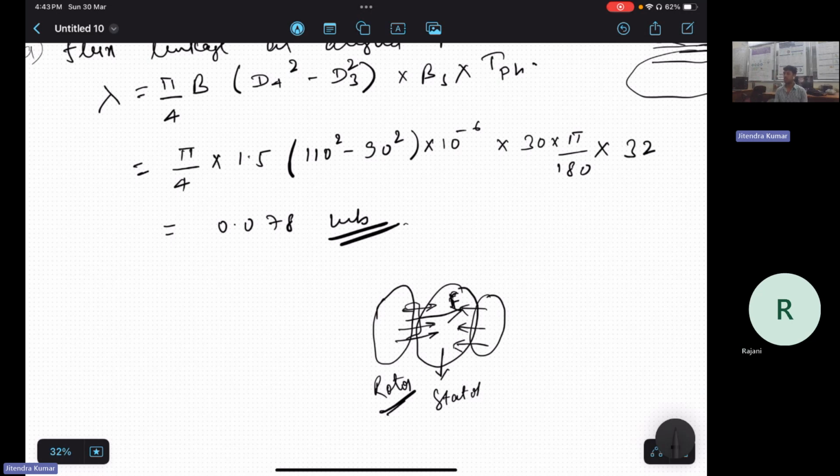You might be seeing many companies opting for axial flux machines, but this machine has existed for more than 100 years. Only now are people opting for such machines. The only reason is that this machine hasn't matured enough because of this unbalanced force, so balancing this machine is very tricky.